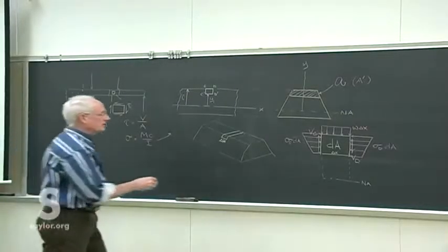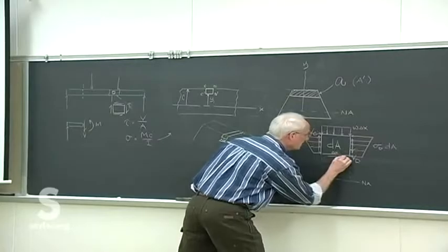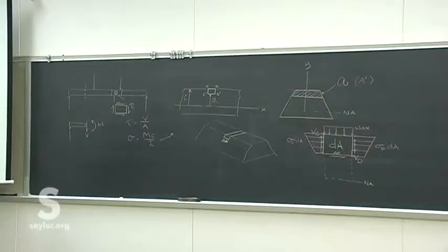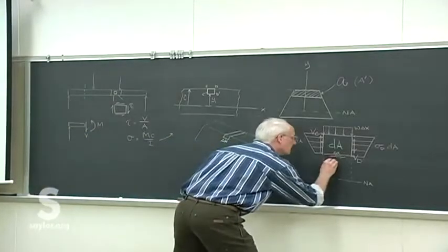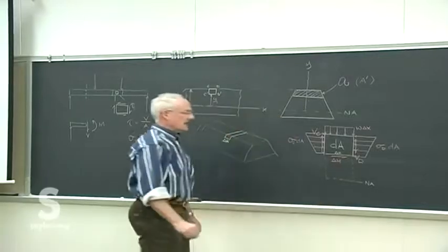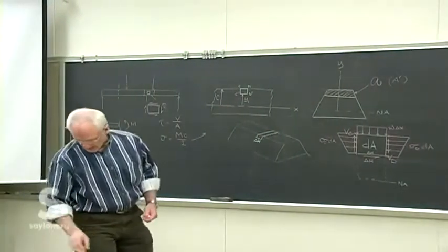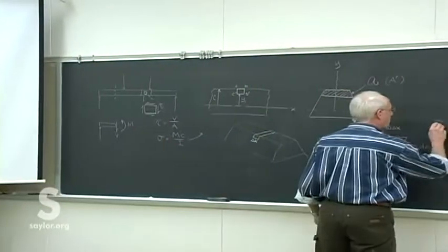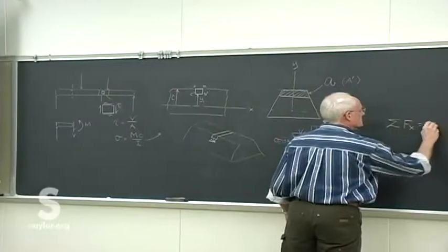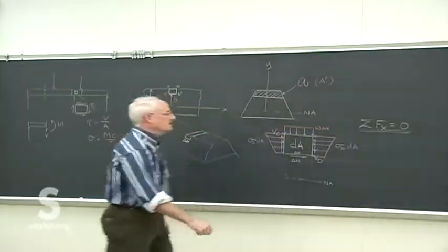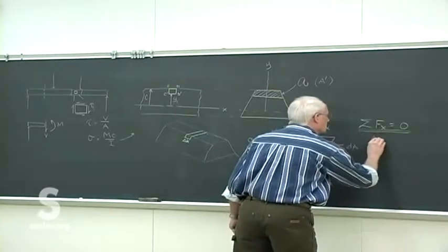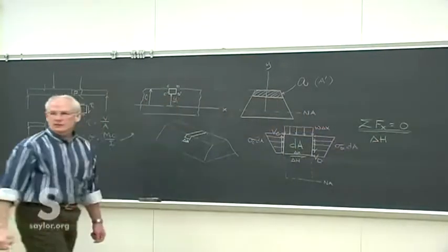And then we've got one last little piece of it, and that's this longitudinal shear that we need to investigate now. We'll call that delta H. God only knows where that came from, but we've got that there. So we'll sum the forces in the x direction, and because of our static limitation, they'll sum to 0. So let's see, we've got delta H, this new piece we're looking for, the longitudinal shear.